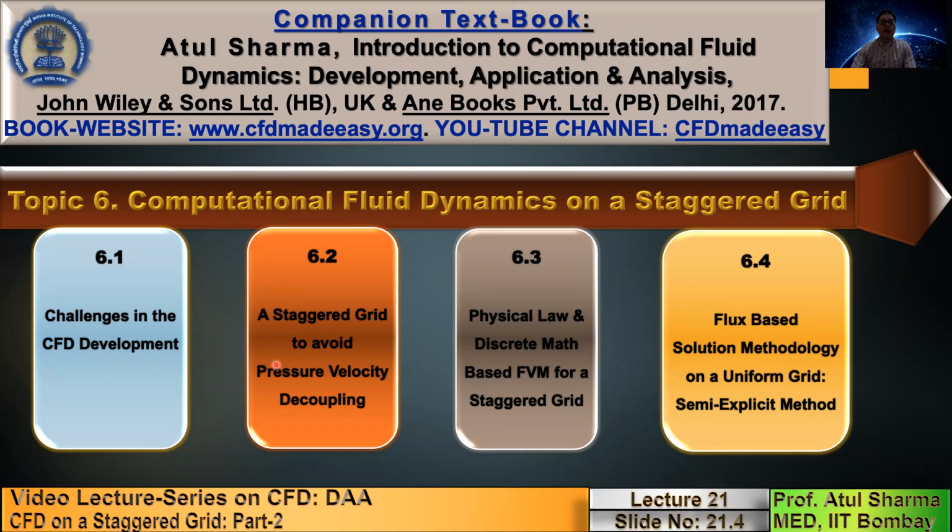And then I talked about one of the first remedies to pressure velocity decoupling, which is called a staggered grid. And then I presented the physical law and discrete math-based finite volume method for a staggered grid.